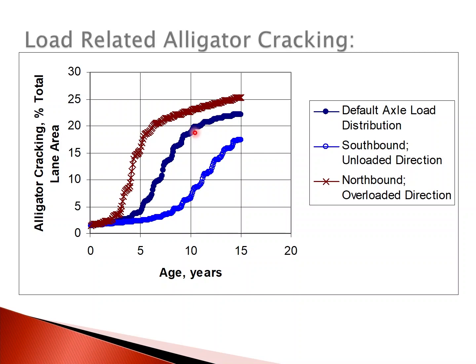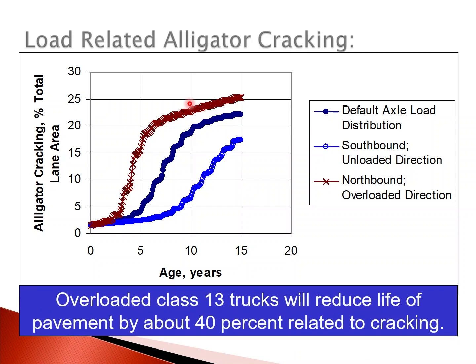So this does make a big difference. Overloaded Class 13 trucks will reduce the life of the pavement by about 40% related to cracking. So it's very significant.